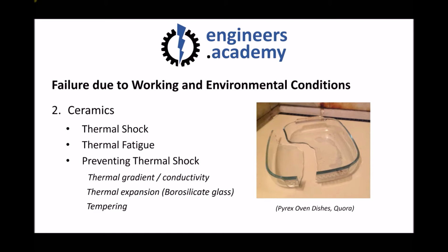And the final method that can be used is tempering. Now, tempering is a heat treatment process, and in effect, it locks internal stresses within the component. So it actually locks compressive stresses within the component, and then when the component expands and contracts, it's working against those compressive stresses. So in actual fact, it's relieving the stresses that are built into the structure of the material.